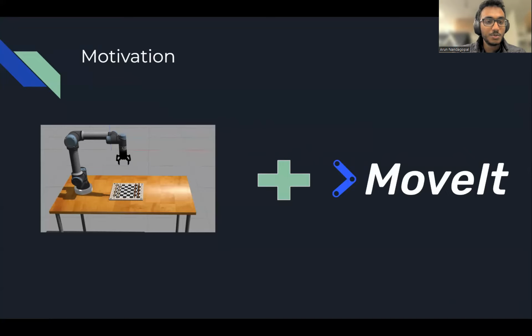to a point anywhere in the space, we can use this library Moveit to do the path planning for us. We do not have to worry about the inverse kinematics and solving them and then moving each joint. Everything would be taken care of by the Moveit framework itself. It's a very convenient tool when we want to do certain pick and place tasks or anything related to moving a robot. We go towards Moveit to do that.